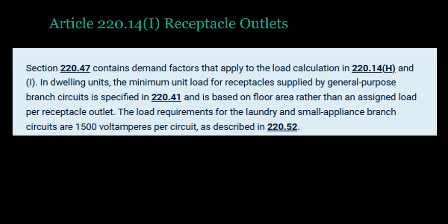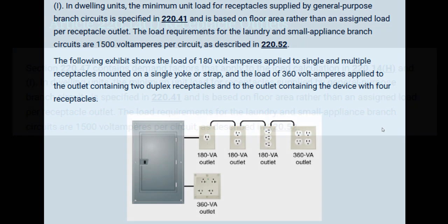The aluminum industry is trying to get back in the game after their debacle in the 1960s and 70s, and they are starting to push copper-clad aluminum. On a 14 gauge copper-clad aluminum Romex, the maximum load you can put on it is 10 amps. But my point is that the loads you're seeing in a single-family dwelling now for lighting have come down dramatically. So that's where that comes from.